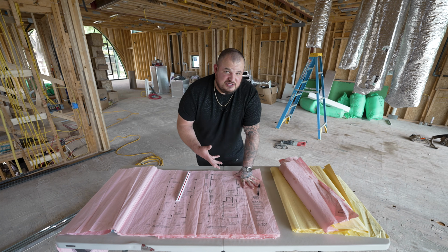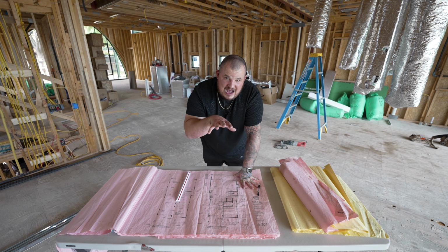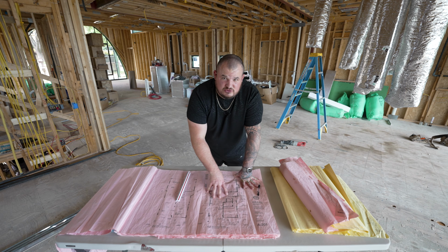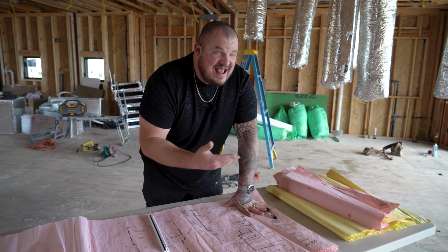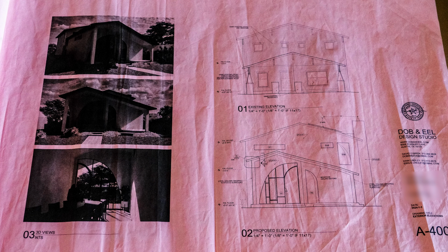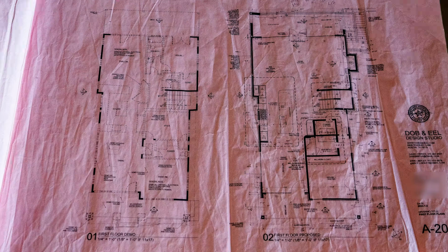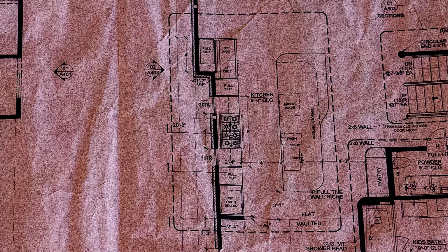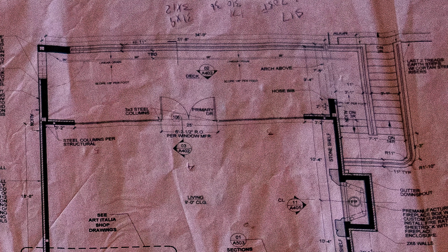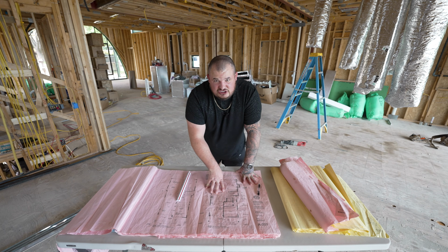Another thing I failed to mention that might not be so obvious is this is a floor plan. We're looking from a top-down view. When we talk about a floor plan, that's always what we mean. Now, when we have an elevation, that's going to be looking at the face of a wall. So this is just to orient you on general locations of where our island is, where our range is located. We have our ovens noted on here. We have windows and doors, things of that nature. But to get a true picture, you're going to want to look at the elevations.